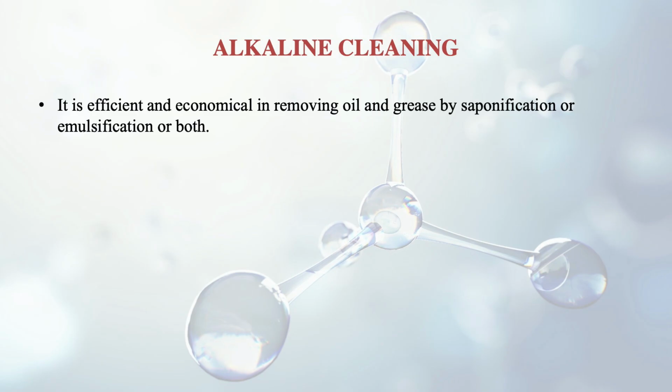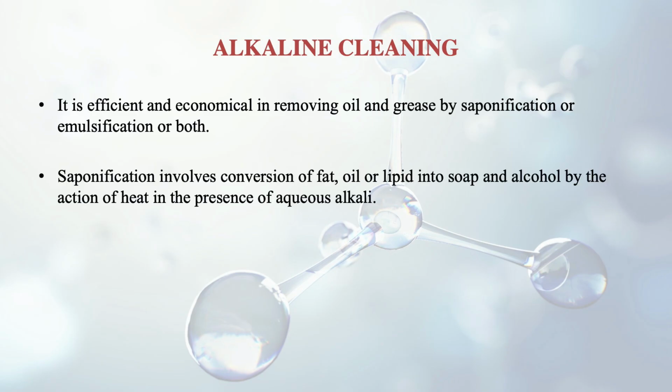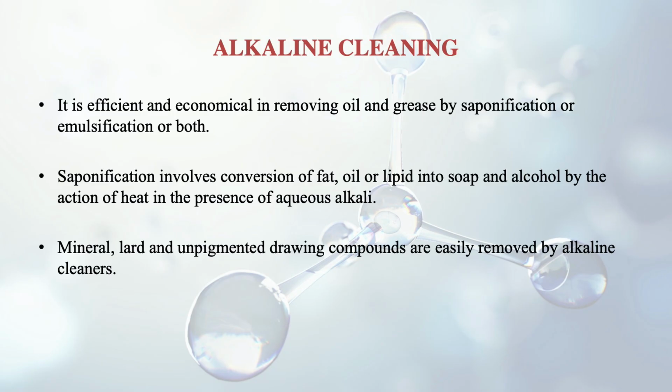First of all, alkaline chemical cleaning. This is quite efficient and economical in removing oil and grease by the saponification or emulsification process. What is saponification? It involves conversion of fat, oil or lipid into soap and alcohol by the action of heat in the presence of aqueous alkali. This is the process of saponification. Mineral oil, lard and unpigmented drawing compounds are also very easily removed by alkaline cleaners.